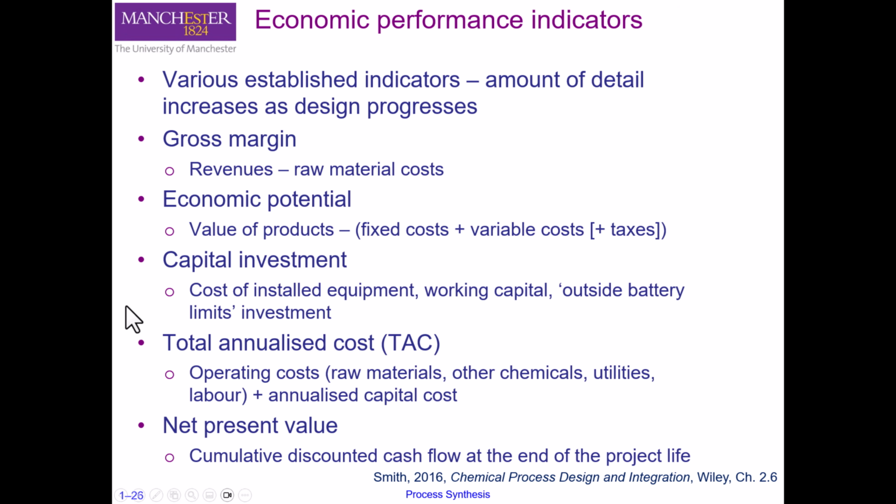This slide reminds you of some of the other important performance metrics for evaluating process design. It is important to identify which performance indicators are useful and meaningful as you try to find the best flow sheet. Defining what is best is often part of the design process, and normally there are different targets that you set for your process, like energy targets, area targets, and number of equipment or number of shell targets. These targets provide one way of defining the best process.